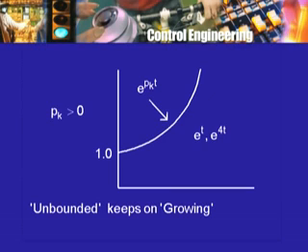Or another possibility is that the differential equation that we assume to hold for the system will no longer hold because of effects like saturation and nonlinearities and so on. Remember magnetic circuit saturation, I told you earlier that as you increase the field current, the field circuit may get saturated, that is, the flux will not keep on increasing proportionately to the field current and it will saturate, it will almost become constant.